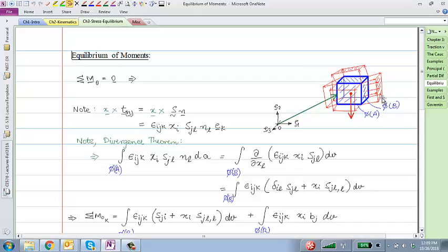No. So of course with equilibrium, when we did sum of moments about some point, the location of that point did not matter. It could be inside a body, outside a body, wherever. So we pick some arbitrary location to be the origin, O, and I'm going to do sum of moments about that point. So can you take maybe 30 seconds and try to write what the equilibrium equation would be?